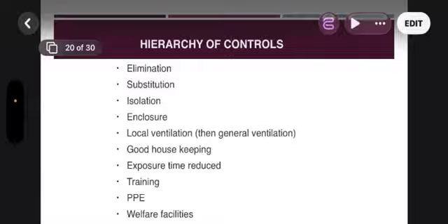Once there is an H2S release, the H2S alarm comes up in a rig. Workers must evacuate immediately. We must be trained to know, because soft H2S, hydrogen sulfide, you can smell it. It smells like rotten egg, and what it does is that it goes to the part of your brain to knock off your sensory organ. It disables it, so you don't smell it again after the first time you smell it. So it becomes normal. Before you know, you become dizzy, and the person becomes unconscious, and it can lead to death.